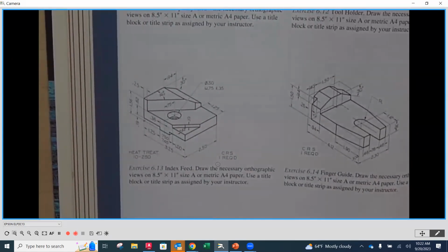Now, in this example, whenever we see tolerances, you do one of two things. If there is a nominal dimension as one of those values, we draw it to the nominal value. So in this case, the high limit of that width is 0.75, which is 3/4 of an inch. If that is not the case, so if the nominal dimension is not one of the dimensions, that's okay. If, for instance, you have the middle number is nominal, and then your high number and your low number are two different values, you find the middle value, okay? That's what you draw it at.